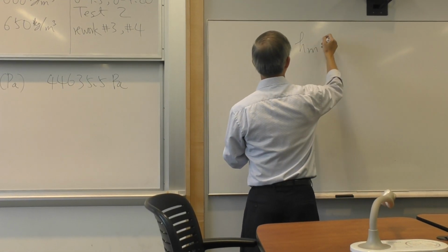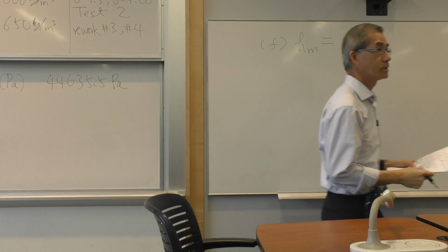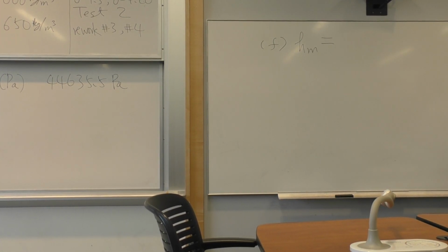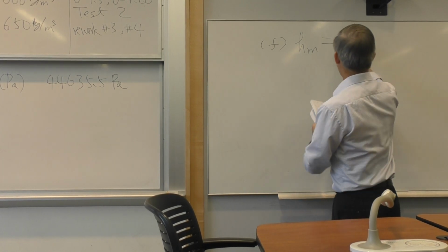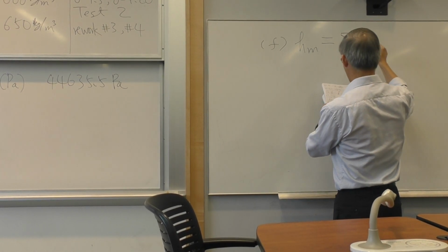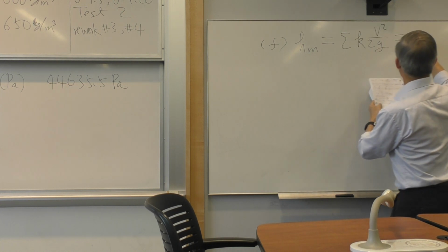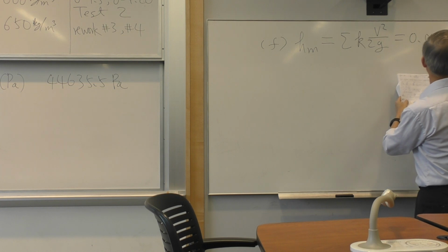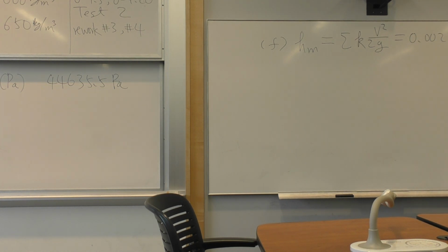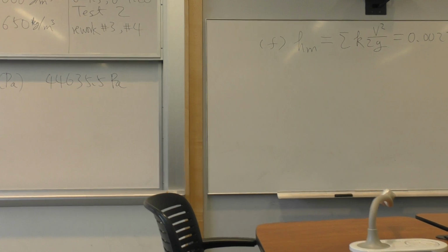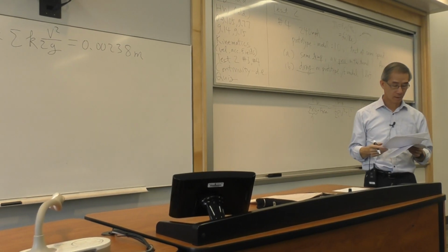what is all the minor losses, which again they're broken up into pieces for ease of getting to the final answer. So the problem actually is broken up piecewise to help you to get to the end. Again, because of the diameter being so big, velocity is so small, all the head loss due to minor component is again very small, 2 centimeters, not very typical of your pipe flow problem. But so far, any question? Very mechanical. This is nothing that you shouldn't be able to do.